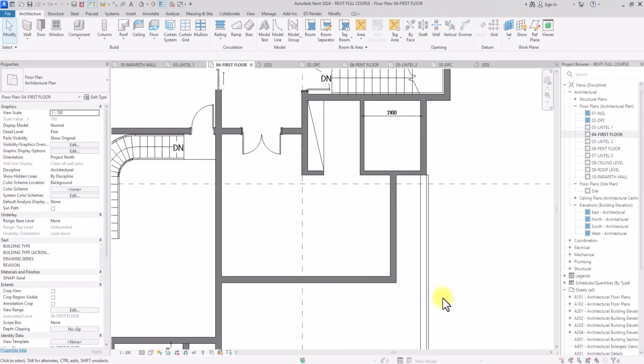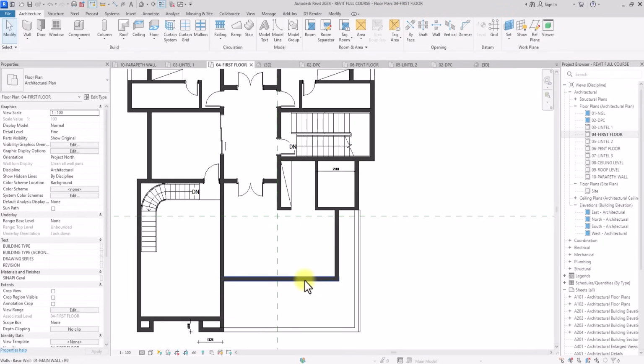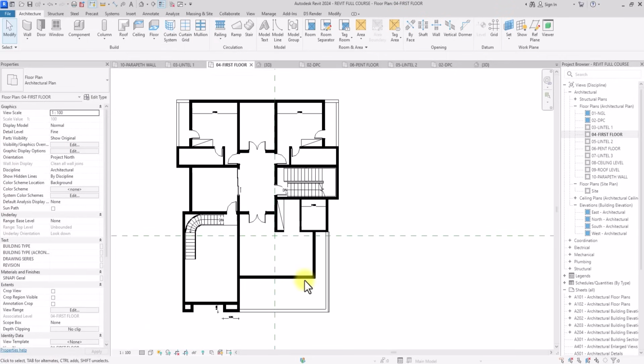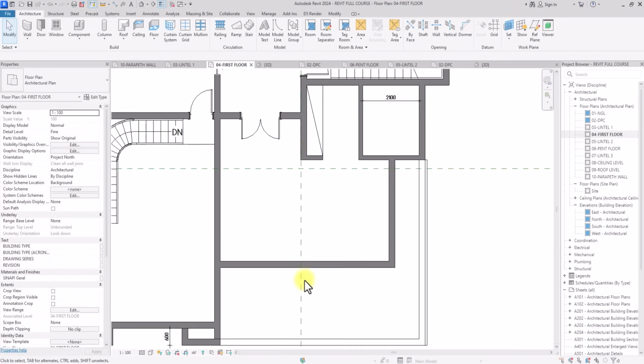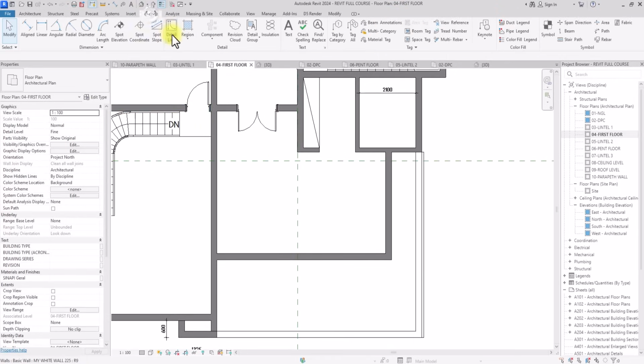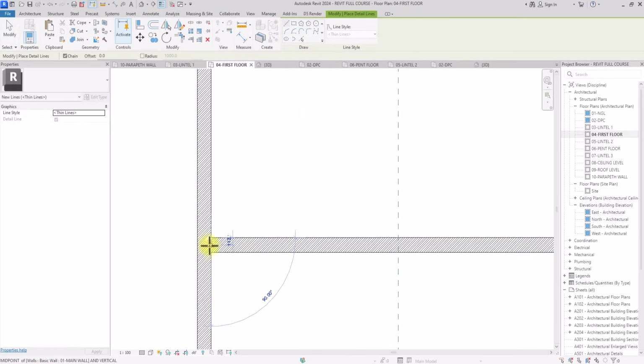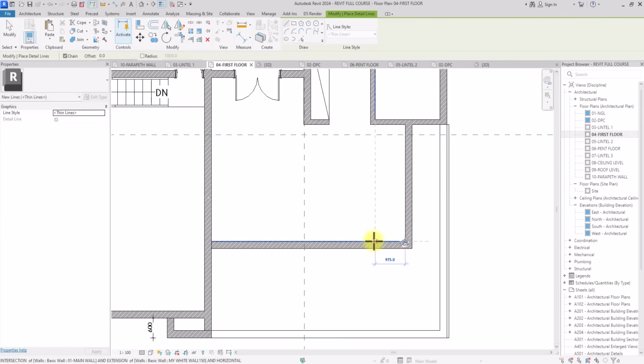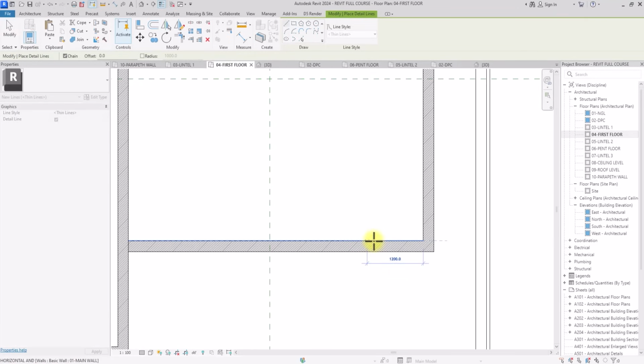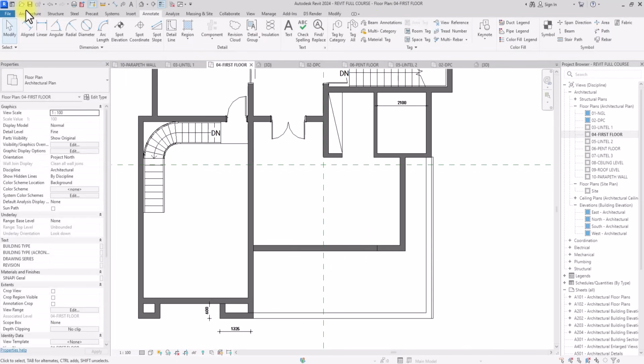So now the next thing I want to do is I want to put a nice curtain wall glazing here, because this place is actually a prominent part of this project. So what I'm going to do is I'm going to, of course, draw a line here, and I'm going to draw another line here where I want it to stop. So I'm going to extend this, let's say 1000, okay, 975, and draw this here.